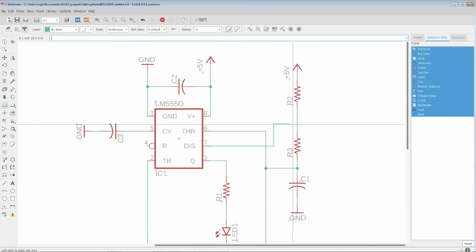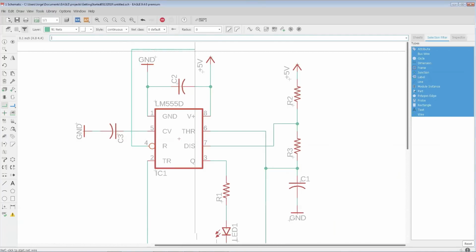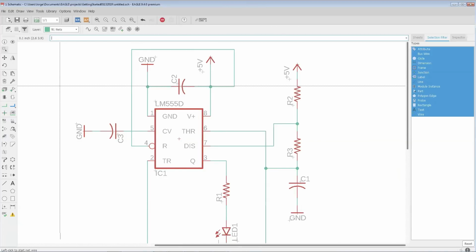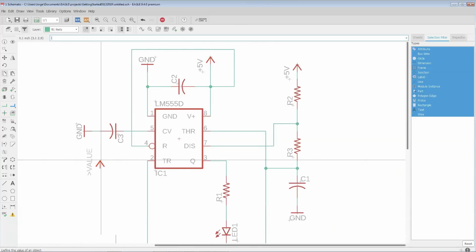The net command is the official command to define your connections on the schematic. Avoid using the line command because that could cause a certain amount of confusion. Always define your connections using the net command. The line command will work as long as you have the net layer active, but in essence, use the net command. Right here, I went around, but I didn't need to do that. What we can do is, again, use the copy command. I'll copy this one over here.